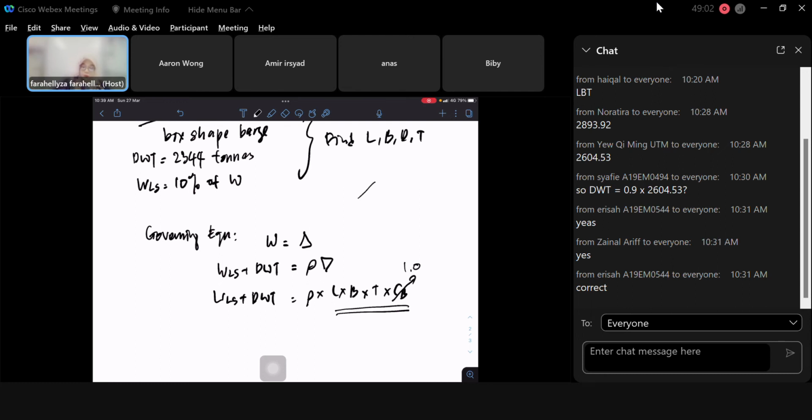You have these kinds of barges. If you are working on it later on, of course, those from SMO have already worked out those equations. But for a ship-shaped vessel, meaning you don't have this kind of box shape, you have a prismatic coefficient, CB less than 1.0. It's more like this kind of shape.